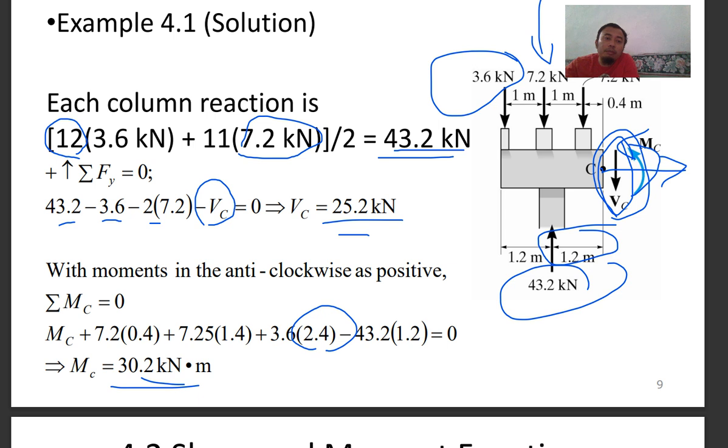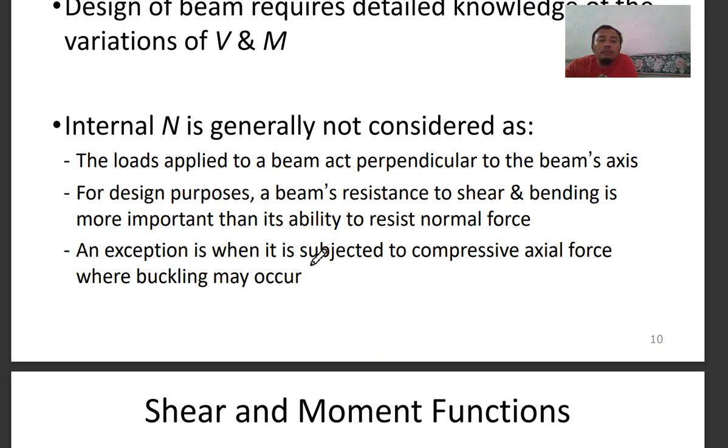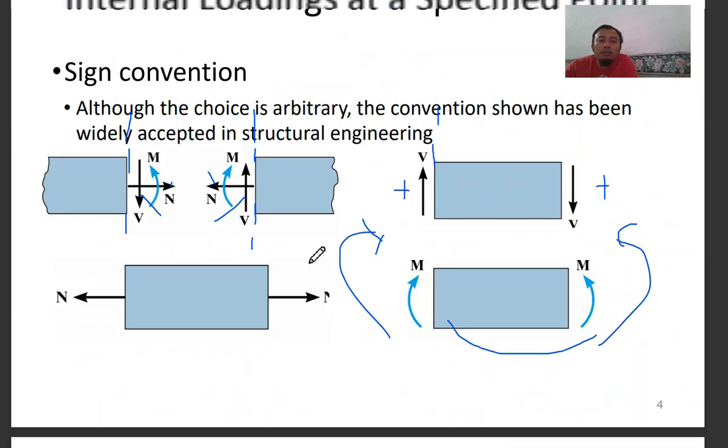But in drawing the bending moment diagram and shear force diagram, SFD, we are concerned only with these two elements, the shear force and the bending moment. So always remember that you assume downward shear is positive, as shown in the previous slide. This one, with downward positive, counterclockwise positive, tension positive.